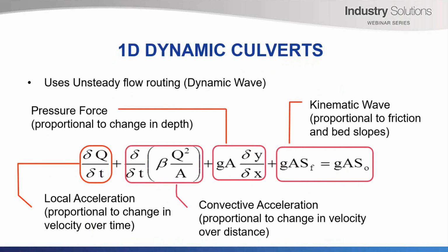This is a 1D form of the equation that we use in our 1D dynamic drainage analysis, and a modified version of this is used for 2D flow in the 2D module. So although the maths has been around for a long time, for almost 200 years, it hasn't been widely adopted because there's no direct solution. So until the use of computers became widespread, it wasn't really practical, and it was generally simplified.